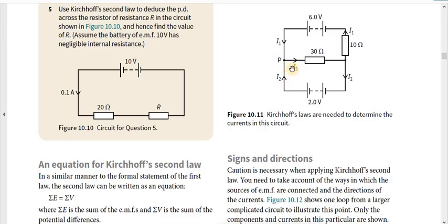Let's say maybe it's a very complicated circuit, we don't know. But if we label the direction like this, we assume it's this way. Let's say it's flowing anti-clockwise here. So we can assume it and label it. And then if we get our final answer as negative, then that means the direction we chose should be in the opposite direction. So if you label the current here anti-clockwise, meaning going this way, then here also you have to label it anti-clockwise. So you have to be consistent.